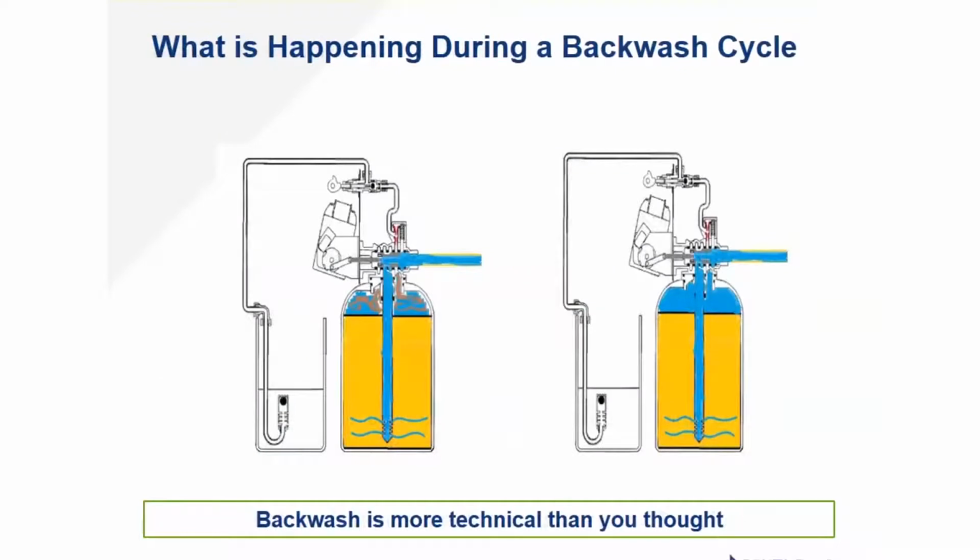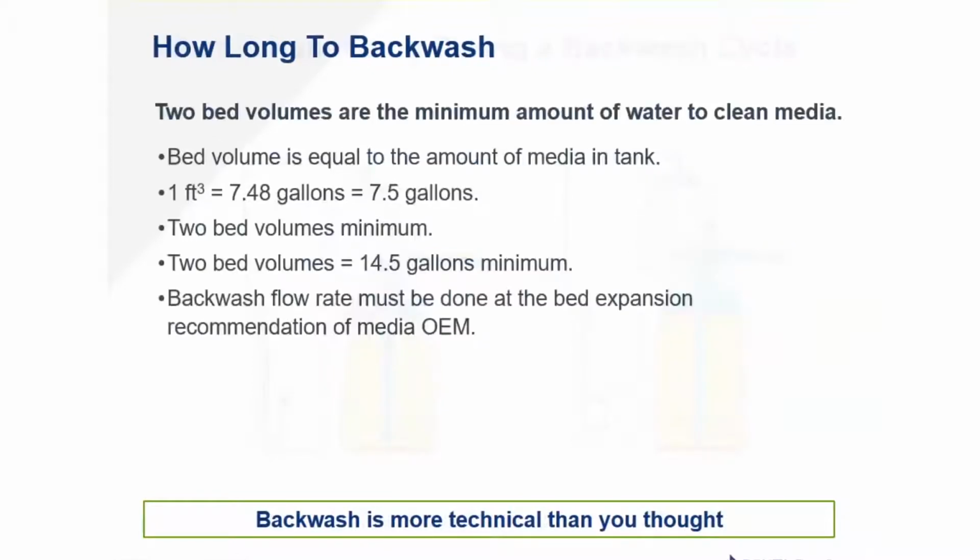So what's happening during that backwash? The water comes down, you start to see the dirt lift off the bed and go out to waste, and it's going to run until it's clean.